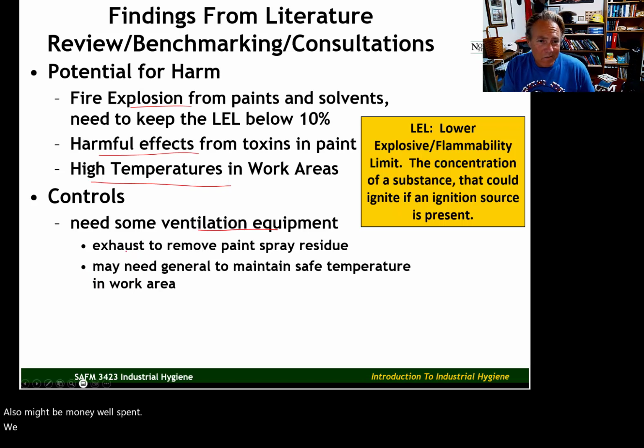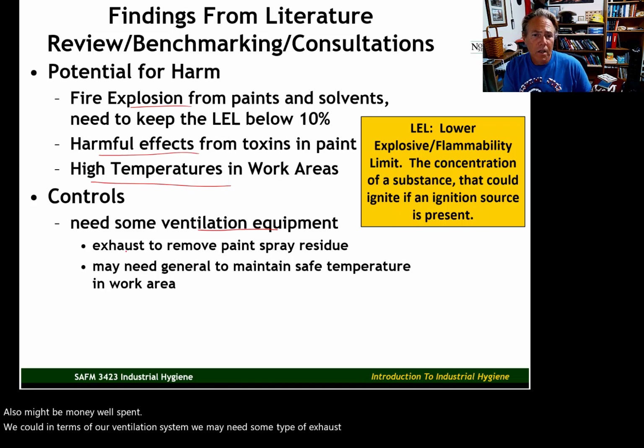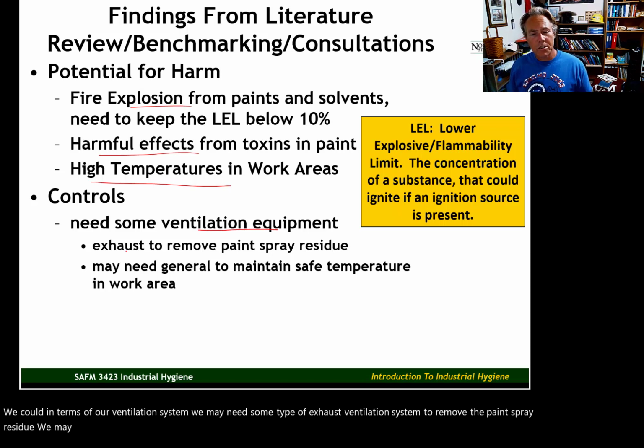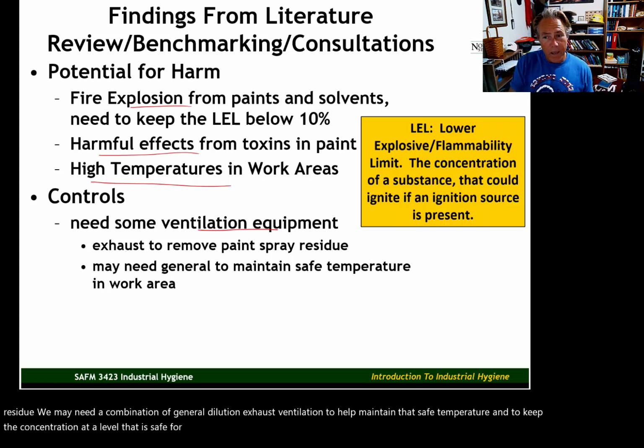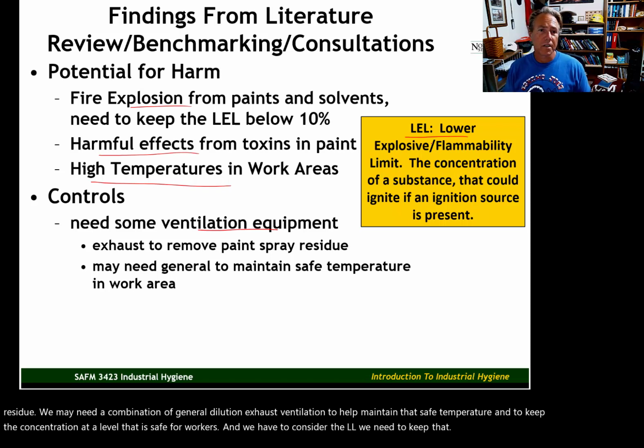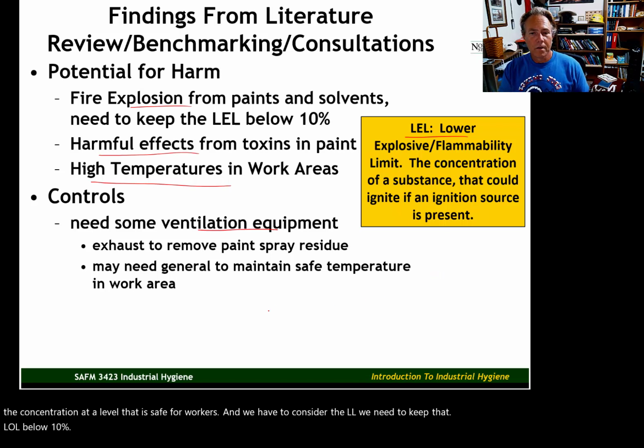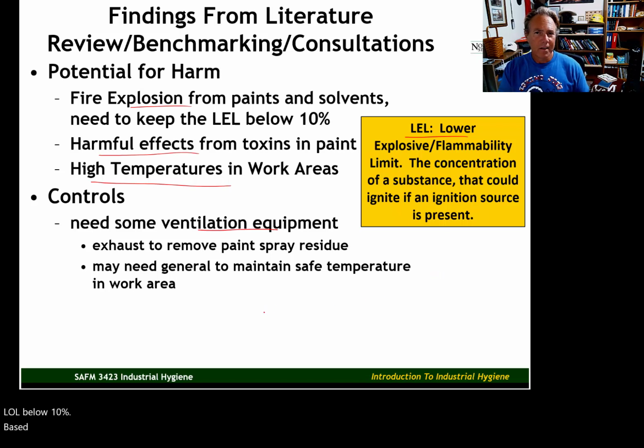In terms of our ventilation system, we may need some type of exhaust ventilation system to remove the paint spray residue. We may need a combination of general dilution exhaust ventilation to help maintain that safe temperature and to keep the concentration at a level that is safe for workers. And we have to consider the LEL. We need to keep that LEL below 10%, based upon the literature that I looked at just very quickly for this illustration.